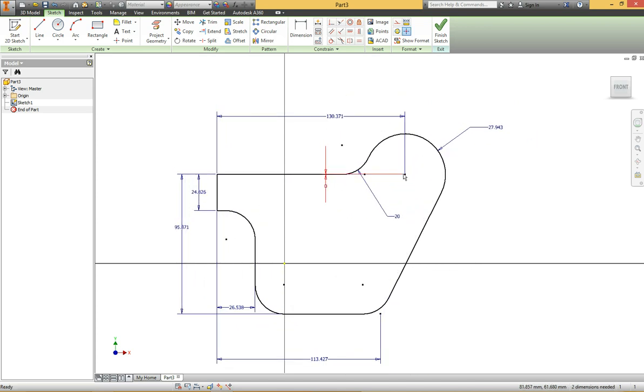And we always want our sketch to be fully constrained so it can't move. Often it's good to anchor it somehow to the origin right here. But it doesn't always work out good that way. So what we can do is apply a fixed constraint to the center point of that circle. And see, that locks its location in an XY coordinate system. And so now we're fully constrained.